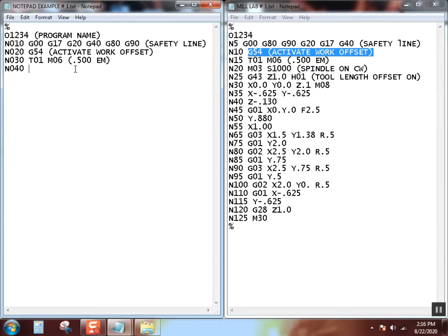Next thing I want to do is I want to turn the spindle on. So that's an M code, M03. Okay, and that's going to always be followed by a speed. In this case, M03 means spindle on clockwise. I will have all kinds of quizzes for you to learn G codes. I will post a bunch of stuff about G codes, so you have plenty of reference material. You just type in G codes any place on the internet, you will get them.